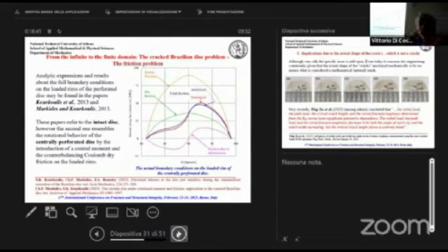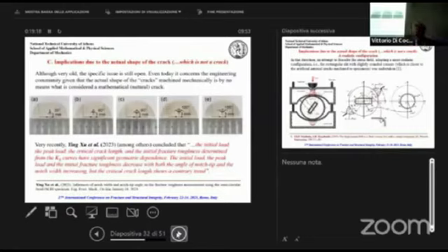It is not Coulomb friction, and it's not symmetric, because the friction should be zero at the axis of symmetry. It is a combination of two types of friction. The first type is the traditional Coulomb friction, and the second type is a friction due to deformation. So if we want to keep overall equilibrium, we should consider the effect of friction forces as we consider it in the case of contact, because avoiding overlapping by inversing the elliptical terms should be used when we also have friction, that is the factor T, as I mentioned. Now, the last issue is some implications caused by the actual shape of the crack, which is not in fact a crack.